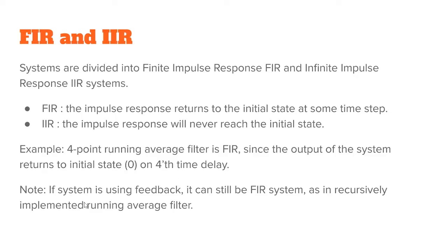Same way, these sampled analog systems are infinite impulse response systems. If you start sampling the step response of an RC filter, it's a never-ending decaying signal.